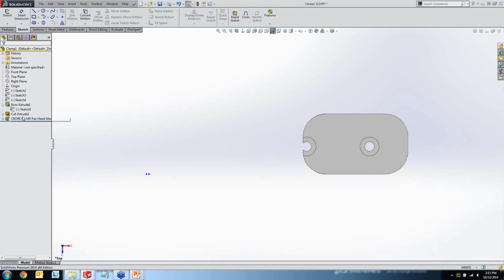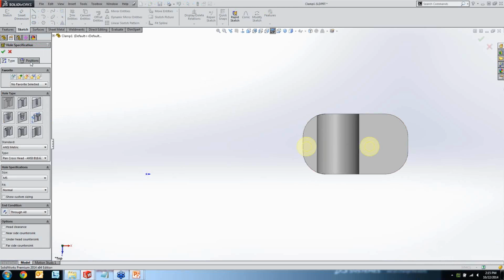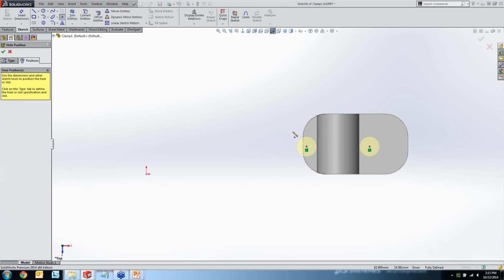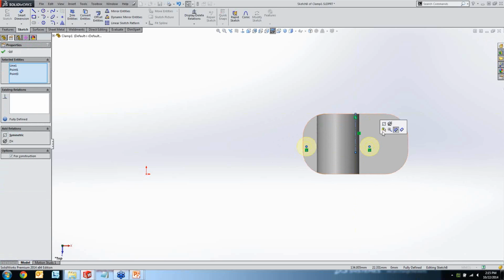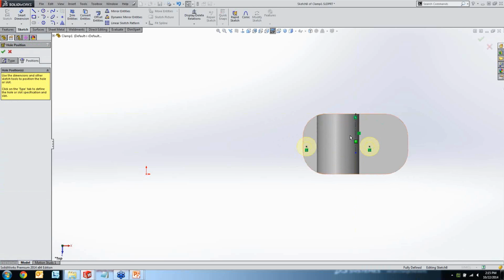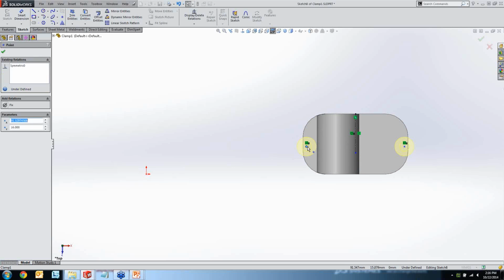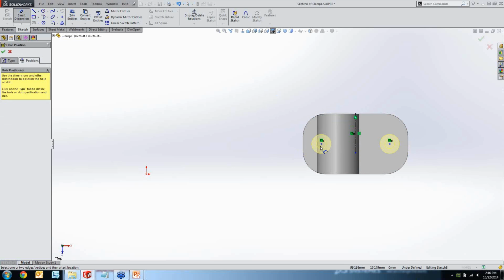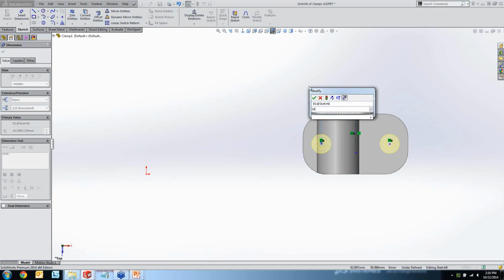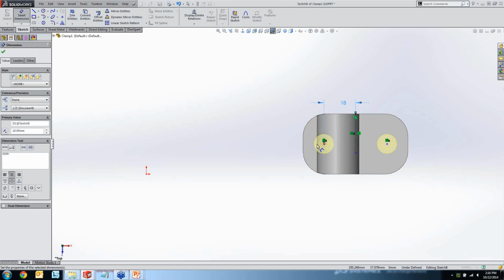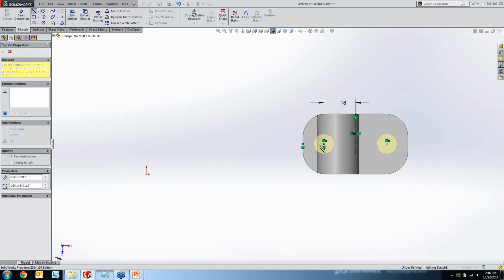Again, I'm going to switch the unit system here to 60 millimeters. We notice that the holes got moved over just a bit, but that's fine. I'm going to go ahead into my hole wizard tool here, and I'm going to simply reposition everything where it should be. So with a few clicks, we're able to easily establish these different changes that we want to make here. Okay, and after we get these all positioned right where we want them, we're ready to start designing this part.